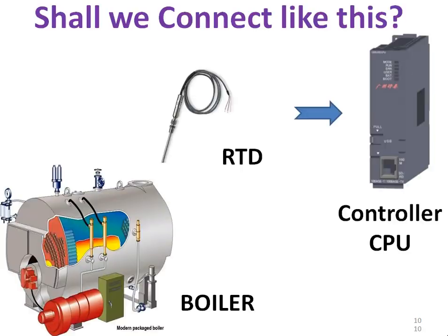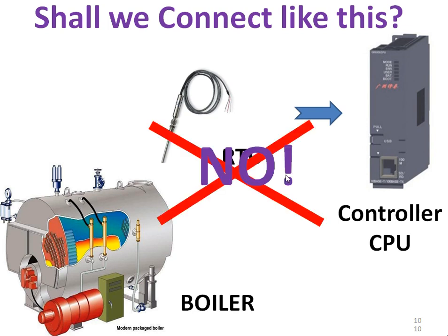Shall we connect like this? So I have a boiler, and the RTD is a temperature sensor. It converts the physical quantity, temperature, into an electrical signal. Can I directly connect the temperature sensor to my controller or CPU? No, you cannot connect directly.